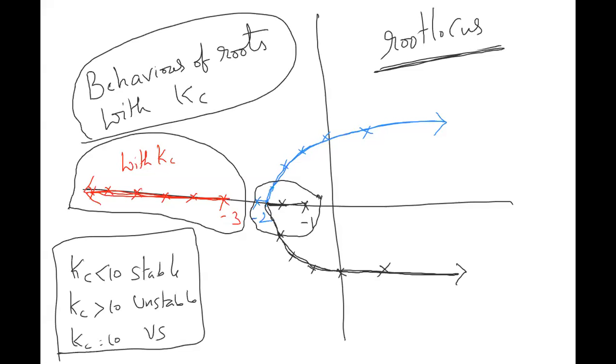That is where you will discuss the concept of Ziegler-Nichols settings in the frequency response, where if you know the value of Kc, let's say here the value of Kc equal to 10 is the upper limit. Kc up to 10 is stable.